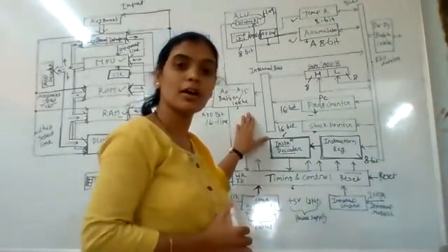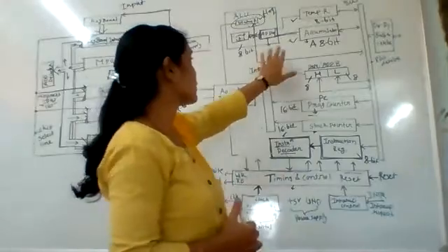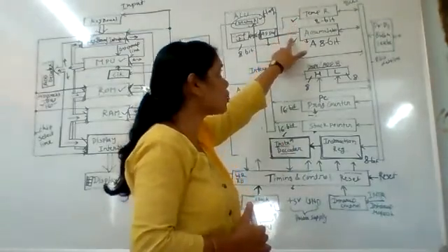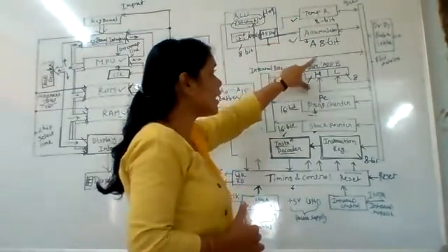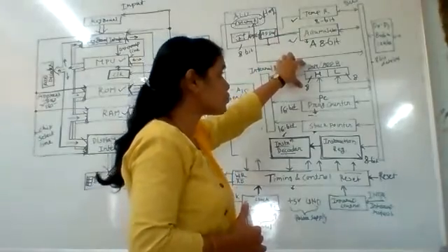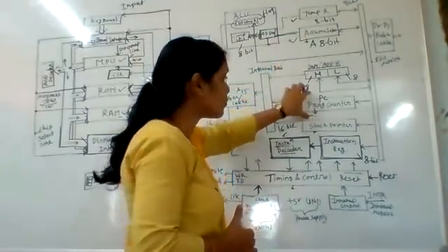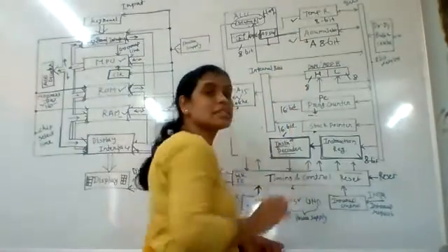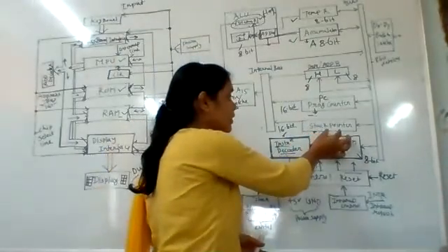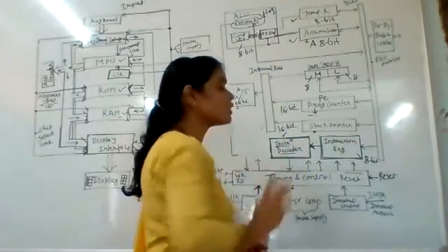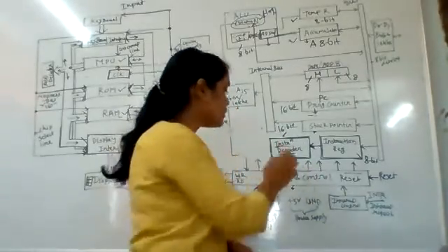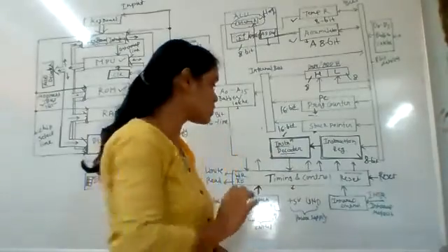This is about the block diagram of a generic microprocessor. The blocks are: the ALU; the temporary register, which stores temporary data at the time of execution; the accumulator, which holds data to be processed; and the data and address registers. The temporary register, accumulator, and data and address registers are 8-bit registers. The program counter and stack pointer are both 16-bit registers. The program counter stores the address of the next executable instruction, and the stack pointer points to memory. The instruction decoder decodes the instruction. The control and timing unit generates control and timing signals for the whole circuit.